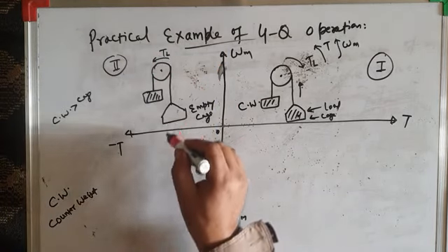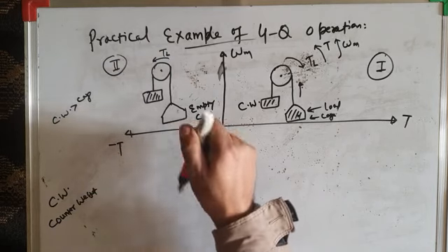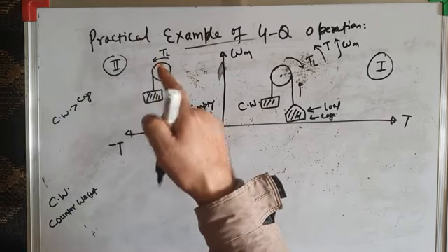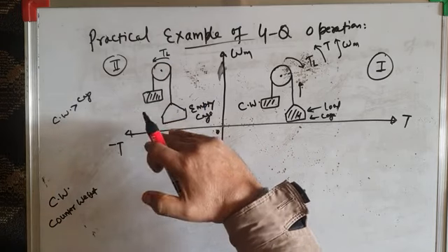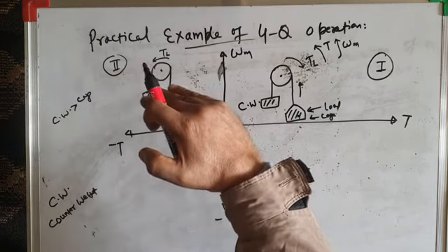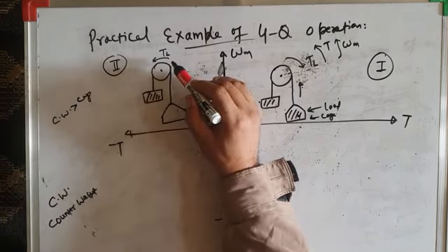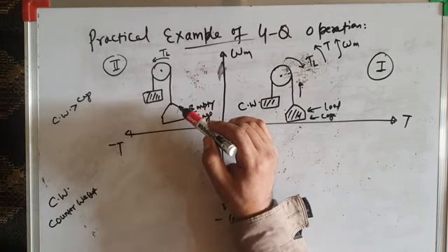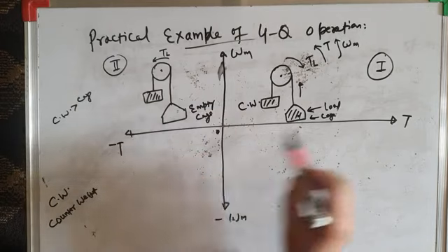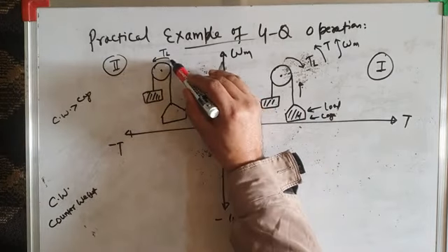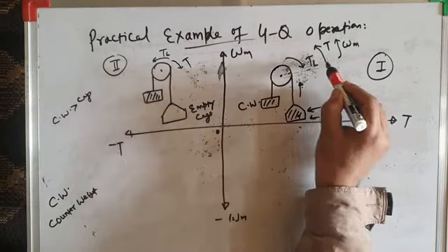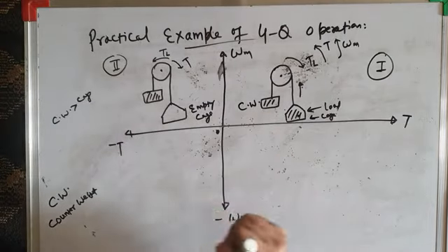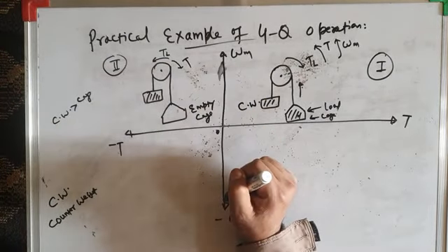But we don't want this cage to move up at a very high speed. We want it to move up steadily at some steady speed. So what will happen is, the machine which was developing positive torque here will develop a negative torque. The positive torque was, say, in this direction, and by convention this is the negative torque.